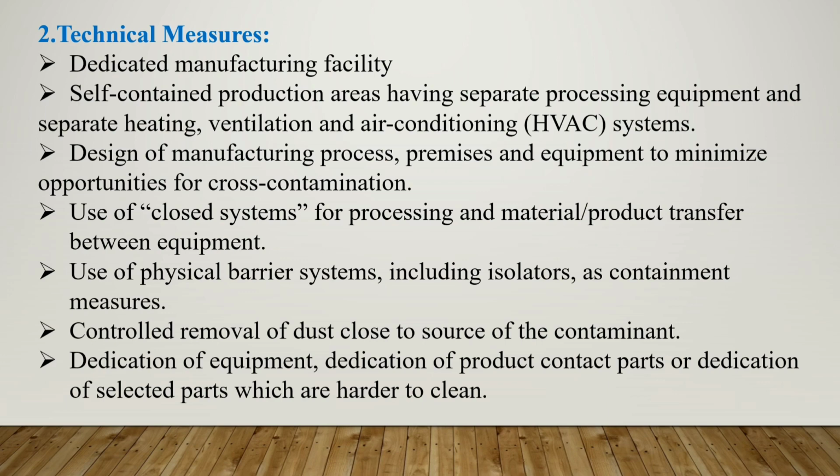In some cases, if your molecule is highly hazardous or practically insoluble, in that case you need to dedicate some complex parts of the equipment for that particular molecule, so you can control the cross contamination in that way. Or you can dedicate the equipment as well as the area for that particular molecule.